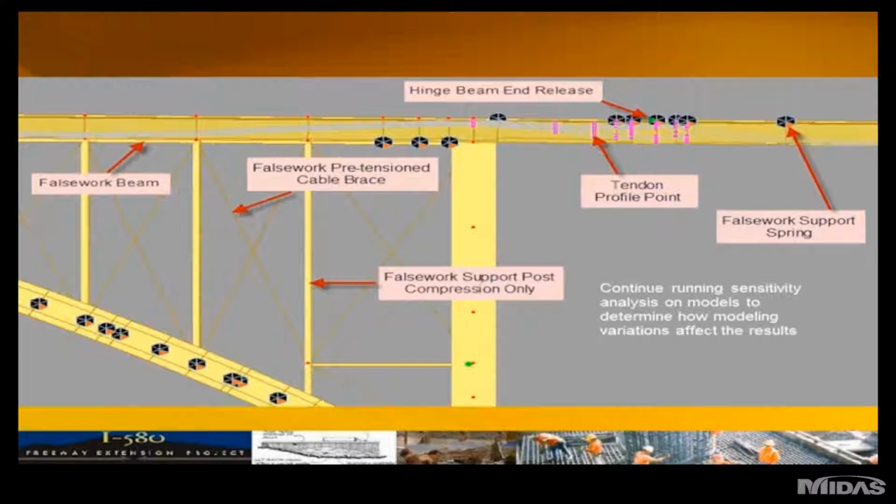You can see the individual tendon profiles; the profile tendon points were constructed as per the actual profiles used on the shop drawings. And as I mentioned, there were a lot of models, and a lot of sensitivity analyses were run to see how varying the casting sequences, stressing sequences, and false work removal would play out. So many different models could be run to verify what the contractor wanted to do.